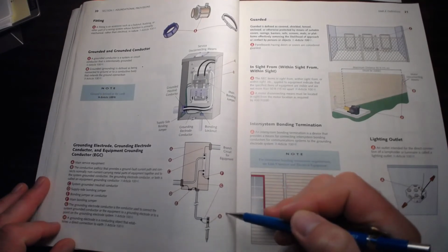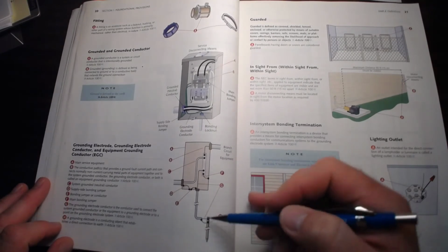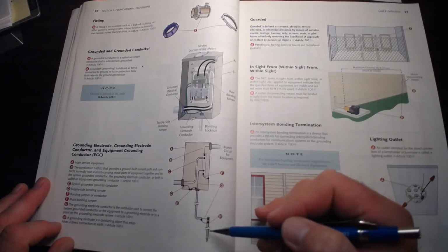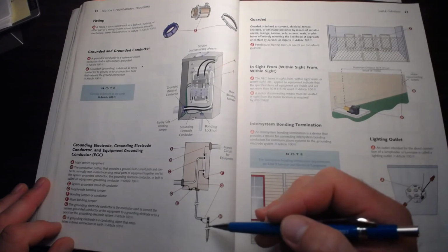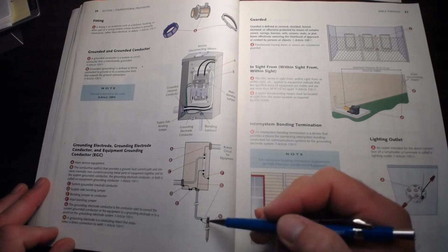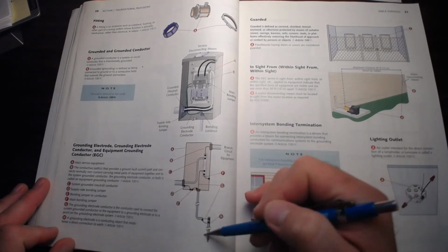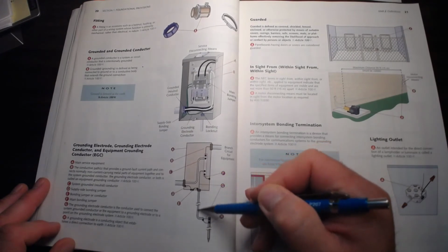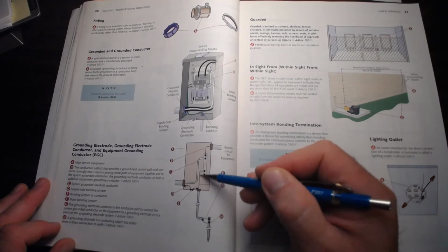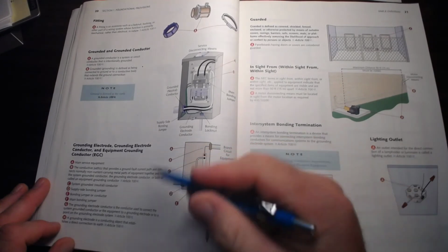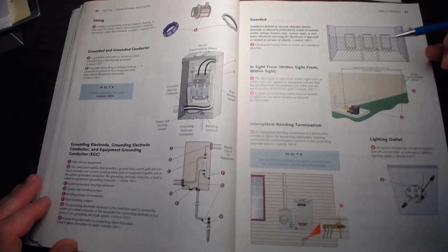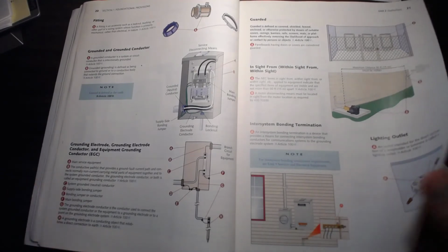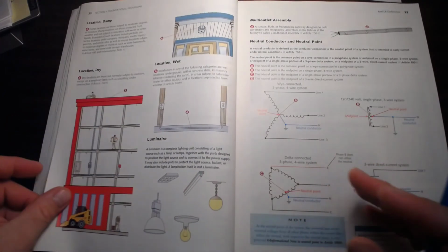The ground rod is a grounding electrode. So the way to keep these straight is the grounding electrode is what you put in the earth to create a connection to earth. Then you're going to connect the grounding electrode to the panel with the grounding electrode conductor right here, and that's going to make a connection. These are terms we will come back to, but you need to be aware of them right now as we start to go into this, because you're going to come across these terms.